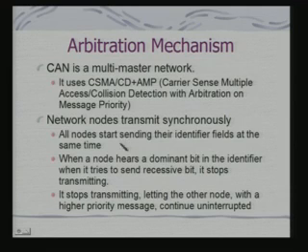So, if you have a 0 over there, that is a dominant bit. Obviously, the dominant bit takes precedence over the recessive bit. So, if I have a message with a higher priority, that message will be transmitted. The collision gets automatically resolved on the basis of message priority. This is something very, very interesting with CAN.